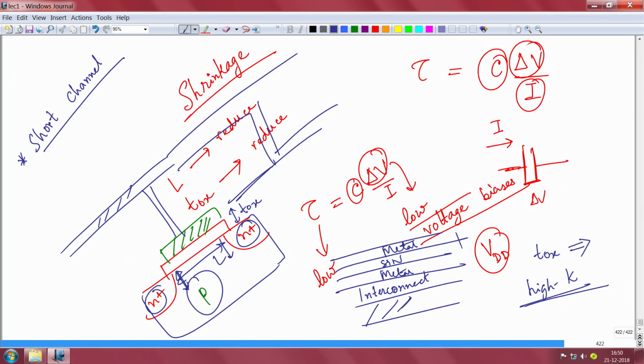For high speed digital logic you need dielectrics with low dielectric constant in this interlayer dielectric, so that the charging discharging delay is smaller. Whereas, for gate oxide you need a high dielectric constant to make sure that you can have thicker oxide and still have lower leakage, and equivalent oxide thickness is high.